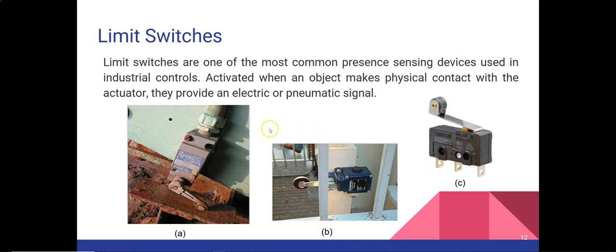But there are two drawbacks of having the limit switch. The first is, being a mechanical device, they eventually wear out, and second is they require a certain amount of physical force to actuate. You can see in this picture, without a force, this limit switch won't be able to work. So that is one of the drawbacks of the limit switch. Now let's move on to the next